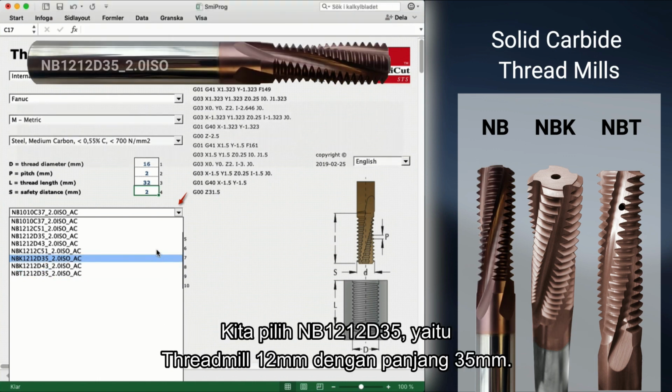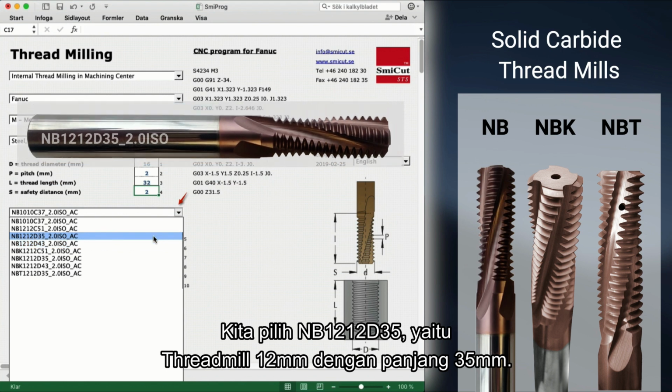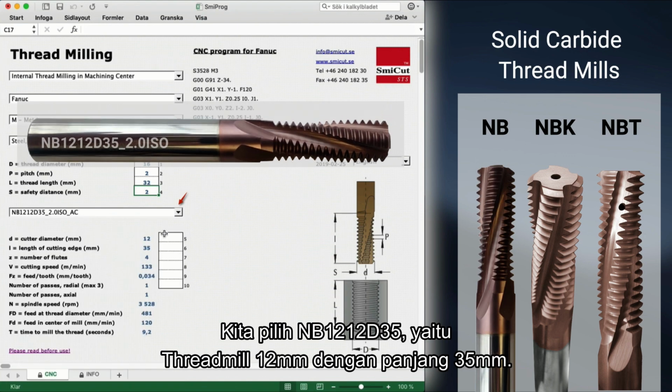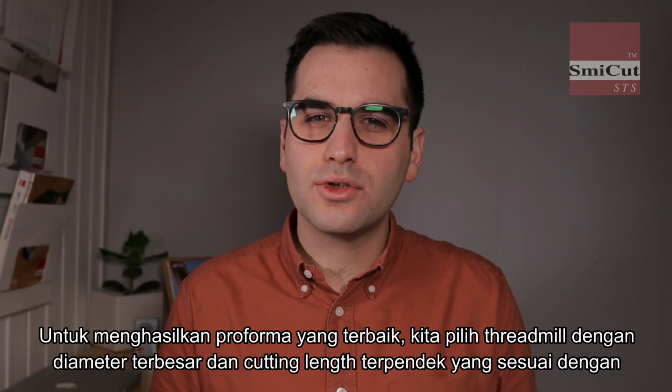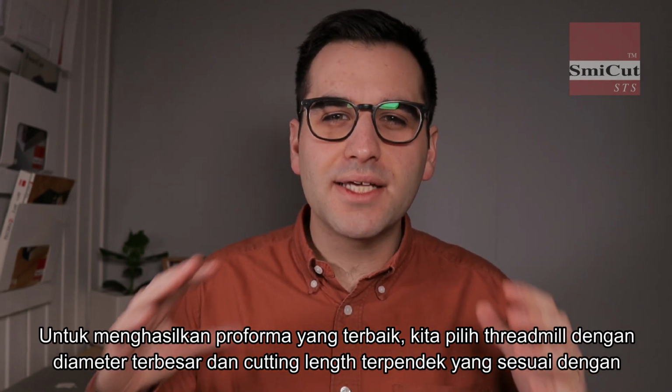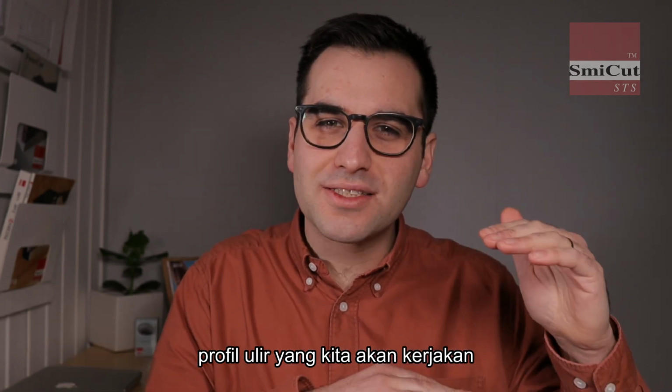We choose this one, NB1212D35. It is a 12 mm thread mill with a cutting length of 35 mm. To get best performance, we select the thread mill with biggest diameter and shortest cutting length.